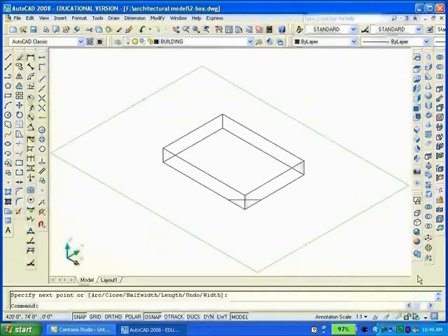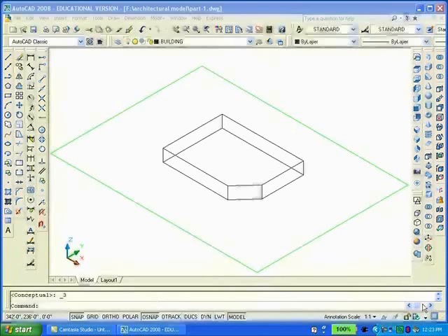And then draw a polyline across the lower right corner of the box. Now we'll enter the slice command and identify the slicing plane by picking 3 points relative to the polyline. With the lower right corner of the building removed, the basic building shape is completed.